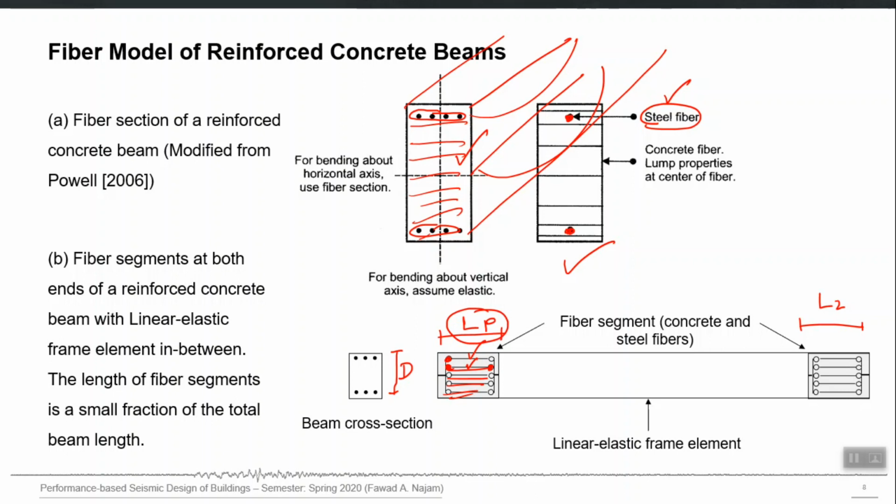This is the length in which you can expect material failure under lateral loading, and different empirical expressions are proposed by different researchers as a function of cross sectional dimensions and of material properties like Fc prime and Fy. You can calculate this plastic length, or you can just decide based on some empirical or thumb rule.